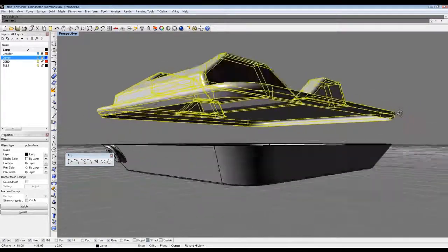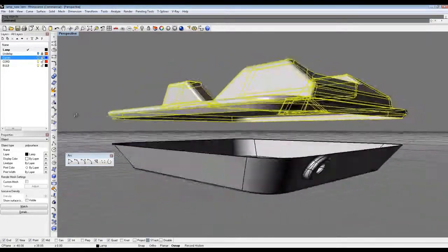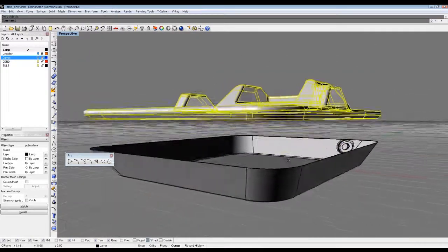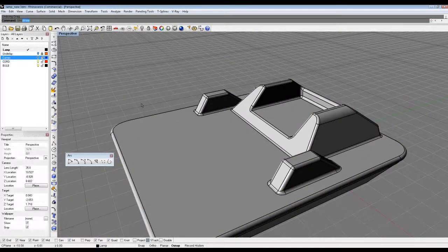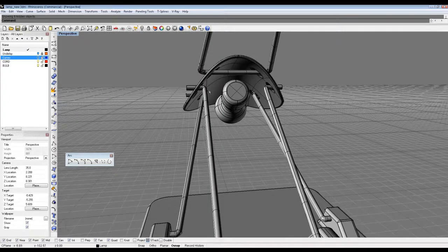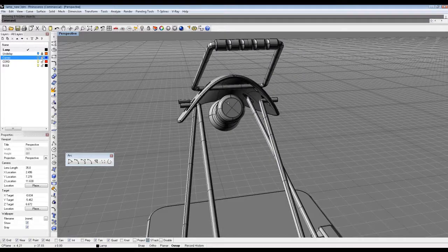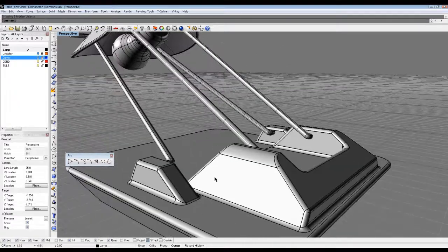I would probably sooner do this on the SolidWorks side to thicken it, but you can start to figure out how your components would fit in there, or obviously a big design flaw with this is how does the lamp stay on top of the lamp shade, because gravity still works. So we'd probably put some mounting brackets in there and run a cable through one of these arms and then down into the base and then out to the power.